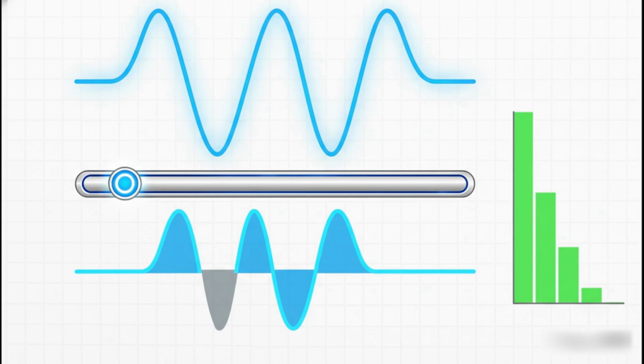Whoa, okay, don't panic. I know this equation looks a little intimidating, but the idea behind it is actually really straightforward. The only thing you really need to pay attention to is that alpha right there. That's our delay angle. The output voltage, VRMS, is totally dependent on it. If we set alpha to 0, meaning no delay, this whole big equation simplifies and the output voltage is the same as the source voltage. We get full power. But as you increase alpha, making that delay longer, you're subtracting a bigger and bigger piece from inside the equation. That makes the final output voltage go down. If you crank alpha all the way to 180 degrees, the output drops to 0. This direct mathematical link is what makes your dimmer switch feel so smooth and responsive.